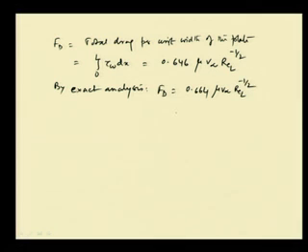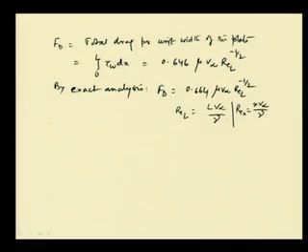We should remember again that REL is nothing but L V infinity by nu, and we know that Rex is equal to x V infinity by nu. Okay. That is when it flows over a flat plate. Now, another part, that is CD, the skin drag coefficient or wall drag coefficient, whatever you say, skin drag coefficient.